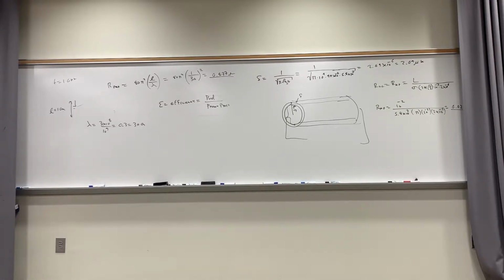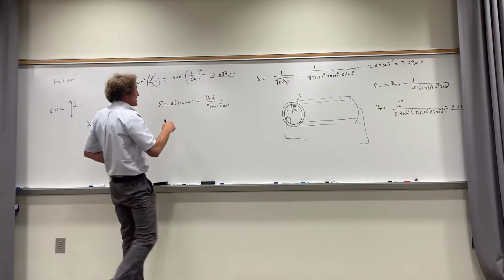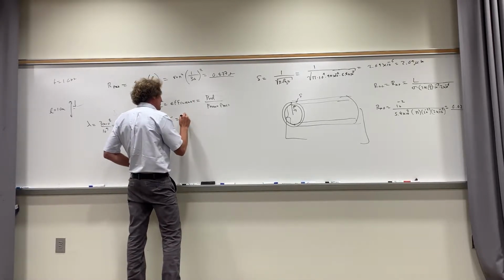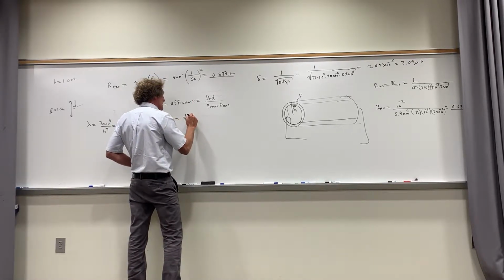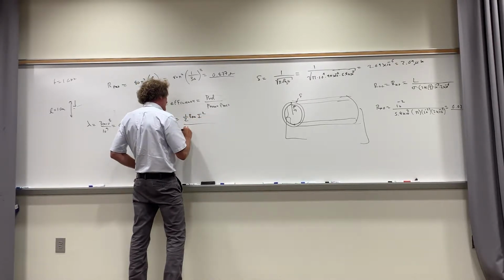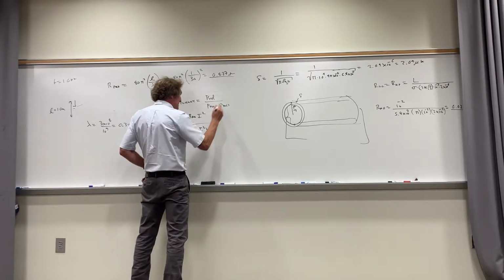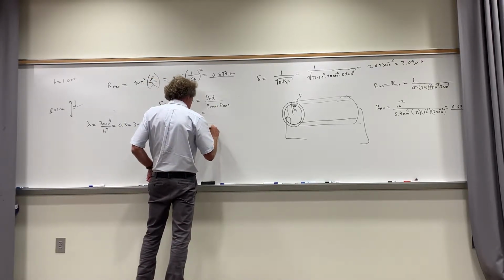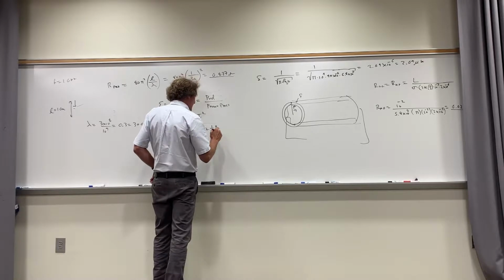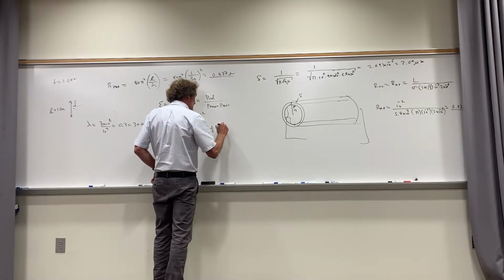All right, well, when I look at this, the same current is going to cause both effects. So the efficiency is really power radiated, 1/2 times the radiation resistance times I squared, over power radiated, 1/2 radiation resistance times I squared, plus the R dissipated. That's 1/2 R, really R high frequency times I squared.